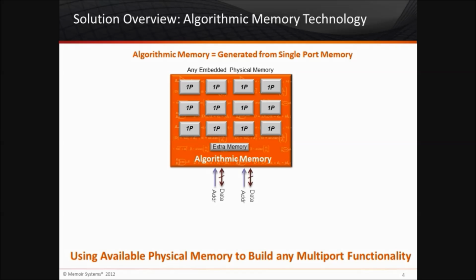And from this is going to follow a bunch of benefits of this approach. Now, an important aspect here is there's no free lunch, of course. In order to make a memory faster, in this case, to go from 1 access to 2 accesses, we're adding some area. A rough rule of thumb is that we add about 15% extra bits and logic in total to give you an extra port of performance. If you wanted to go to 3 ports or 4 ports, you would continue adding a few more bits and a few more gates to give this emulation. At Memoir, we build products that go up to 4x in performance. These are our standard products, but we can go all the way up to 10x in performance, of course, subject to implementation limitations of the RTL.